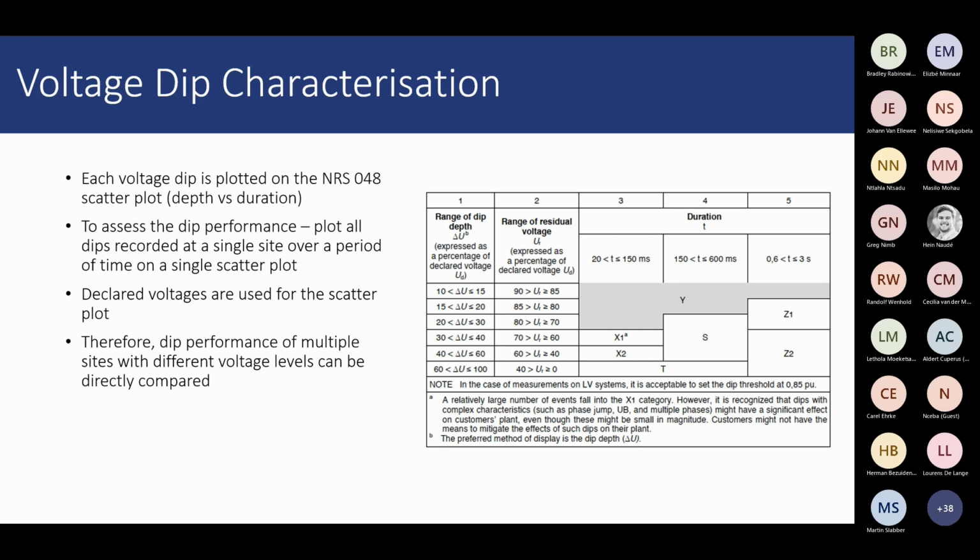But how we would test it on site or practically, we would make the upper limit the lower value. We would put the lower limit value on that upper value. So for the upper limit or upper threshold, we would put 93 and not 107. So already when you click apply, then that relay will not close immediately. It will wait for at least 10 minutes, because it will wait for the next 10-minute average value, and then it will compare that value to your threshold. Because obviously you have set your threshold now to be 93, and let's say you are measuring 110% constantly, then your threshold is 93%. Already you expect to get an alarm.